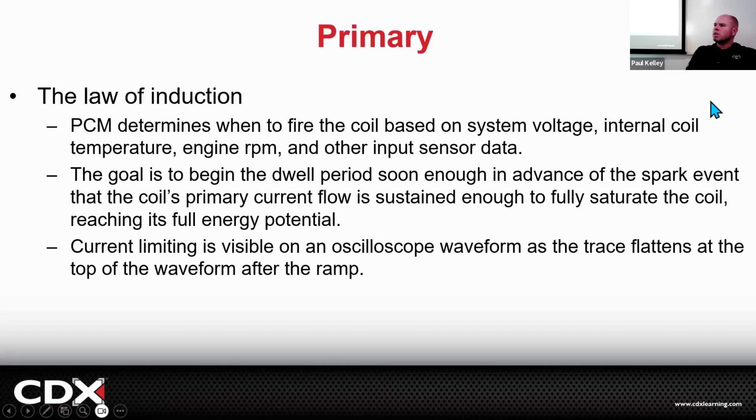So if we start it soon enough and we leave it dwelling, that means giving it 12 volts in ground. That means the ground is connected. If we let it dwell long enough, it'll reach its full potential. Now, there's a couple reasons that that's important. That means we need to very quickly close that ground and let it start to charge up and increase the dwell time. But it takes time to close it. So we've gone mostly to computer control. The computer can close the circuit much quicker than like a physical contactor, okay?